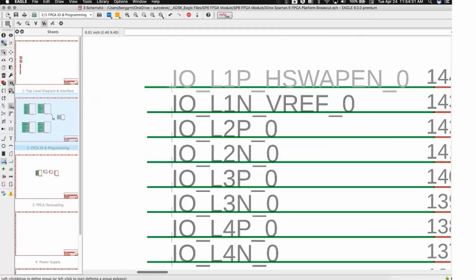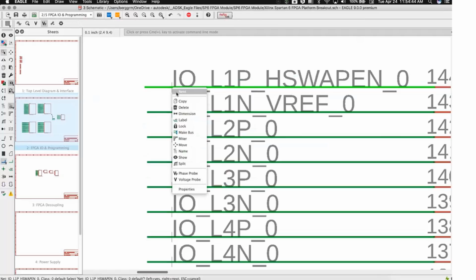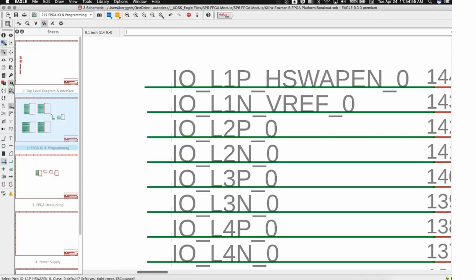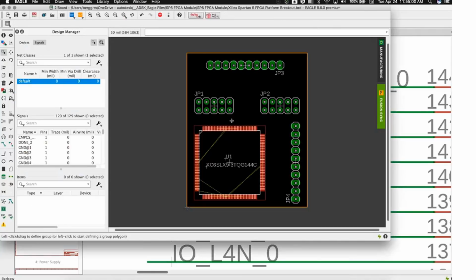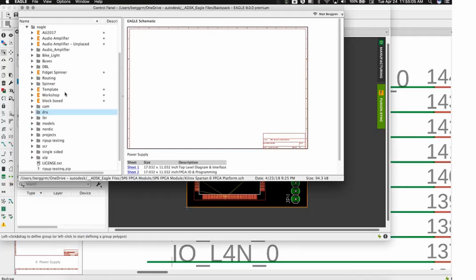You can see now, if I hold Alt, it's basically cycling through what's selected and what's not selected at the coincidence of the two objects. The other, as George mentioned, is you've got Next there in the right menu. You can just right mouse, left mouse, kind of interplay down there, and the taskbar down below will show you what your options are as far as selecting different objects. Probably easier to see on the PCB side of things when you've got a number of coincident objects on board. But there's a number of different options that are in there for sure.